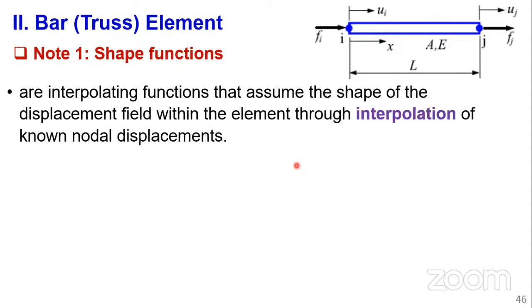You see, I explained that the finite element method is an approximation method. So exact values are only at the nodes. Anything else in between, we interpolate. And we assume a displacement function, the one we have already derived for this bar element. We said the value of u1 will be known, u2 will be known. Any other value here can be interpolated.